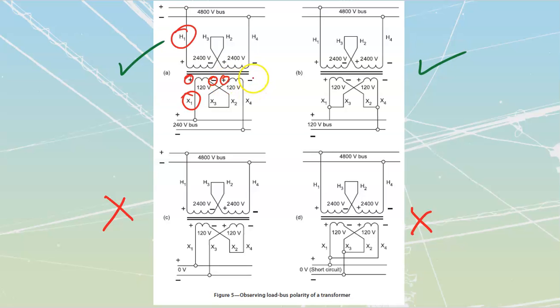If I've got a positive here, the other side needs to be a negative off of there. So what I can do then is take these voltages. What are these voltages? These are generated voltages over here. Remember, on the high side they were counter EMFs that we were pushing back so that this thing wouldn't act as a short circuit. Now they're going to be generated voltages through EG is equal to BLV, because we got this full flux passed through from my primary side.